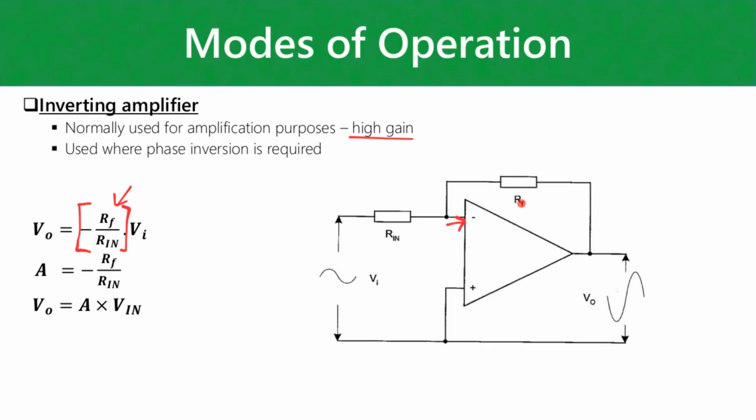And yeah, so one of your design considerations, by the way, when working with amplifiers is to just keep in mind what your supply voltage to the op amp is as well, because you can't amplify more than the supply voltage, right? You will violate the laws of energy if you somehow manage that, which, by the way, you will never manage. But anyways, you can actually then simplify that formula for the output voltage as gain times the input voltage.